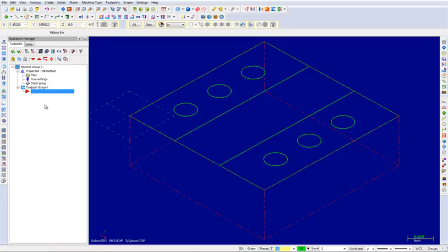To start, we will machine the two steps using Open Contour. A contour toolpath removes material along a path defined by a chain of curves. Contour toolpaths only follow a chain. They do not clean out an enclosed area. From here, select Toolpaths, Contour.